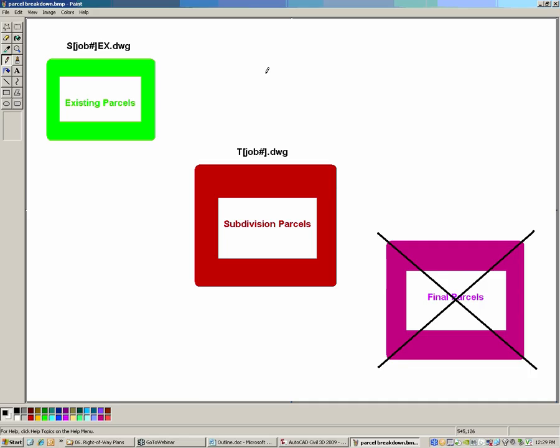Parcels was a pull-down that you'd use to get areas, maybe, and generate legal descriptions, but nobody actually used the line work from that pull-down. You drew the stuff in with polylines, maybe made parcels. It was almost like a piece of data that you never really used to show on the plan sheet. Well, in Civil 3D, you actually see the parcels.